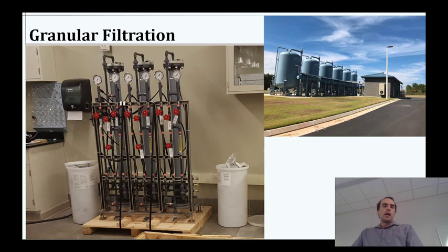Okay, so in terms of granular filtration, there's a few ways to do it. Most of what we'll talk about is like having a bed type reactor, but I just wanted to highlight real quick, there's also what we could call a column or a packed column. So over here, these big columns, those are granular filtration units. These beds are in these cylinders, and we can apply a little bit of pressure that way, more so than if we just have a flat bed.